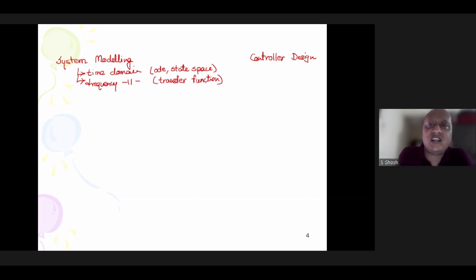Now, the problem with designing a controller for real-time systems is that in most of the universities, we are teaching control theory in the 5th semester. That is the first basic course on control system. Now, the problem is that whatever theory we are taught for control systems, 99% of the time, we assume that the system is a linear system. It is a time invariant system. But in the practical world, 99.9% of the systems that we actually have to work on are non-linear systems, they are time varying, and not only that, the non-linearity is of a very higher extent.